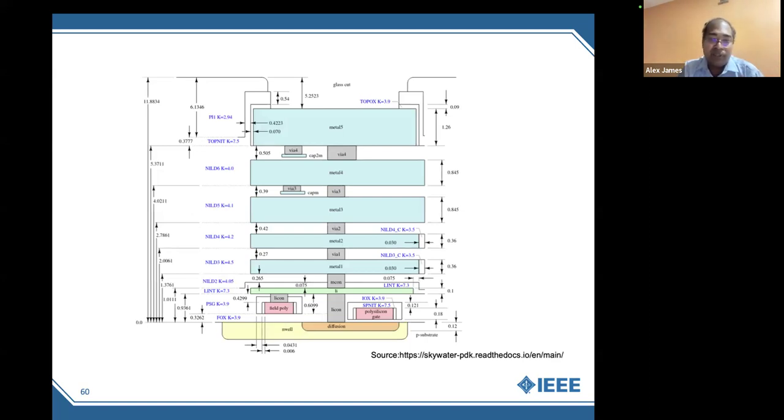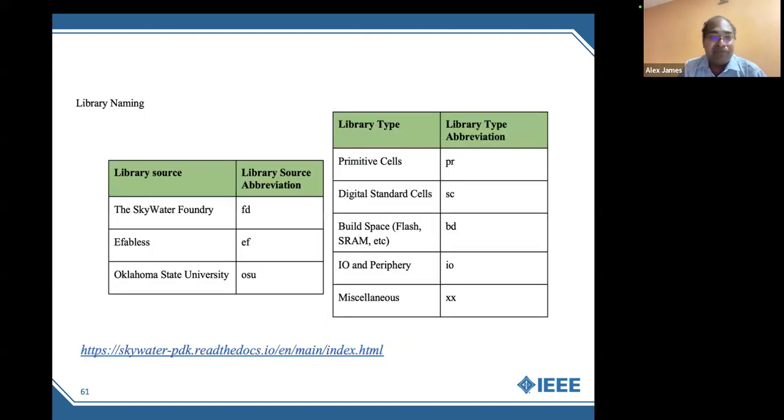If you are working with memristor related things, one thing that you have to understand with the Skywater process is that you cannot do multiple layers. It's basically one layer that you have to work with. So if you're trying to integrate a 3D stack or things like this, then you need to reimagine how to place that. In one of the works we did, we used a folded structure. It's still 3D, but it's between two layers in a folded structure. At least you can demonstrate the concept. So that kind of thing can be done.